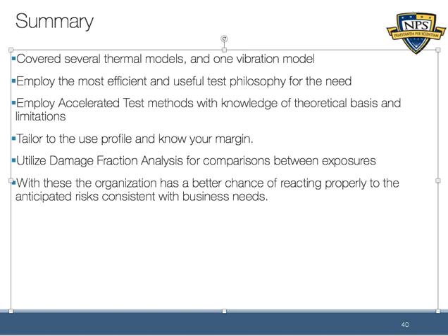Or maybe instead of looking at one life, a lot of times what we do in reliability engineering is look at 3 lives. There may be 1,000 cycles at a delta T of 50 in reality, and you want to find out, okay, that's 1 life, what is 3 lives, and then what would be a test I could design for 3 lives to make sure that my system doesn't have any of these failure mechanisms in it. But there are other opportunities too, where you may find a failure mechanism either in the field or in manufacturing, and you also want to understand what's the risk to other units seeing this. And so you can design a test, again based on lifetime, to understand whether that's going to occur or not.